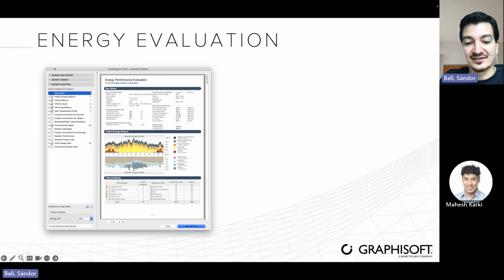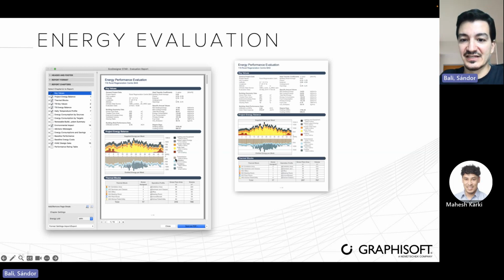Winter time, we have actual heating. And what is balancing this one out? What are the losses? It's the transmission through the structures, the infiltration through the gaps, the losses through the ventilation, and also compensating for these extras with the cooling during the summer months. So we can see that here solar heat gain might be too much because we need to cool it down. So maybe we could do some shading here in the summer, and we could also improve our structures so that transmission loss is not that high. So these are just very quick evaluations here.